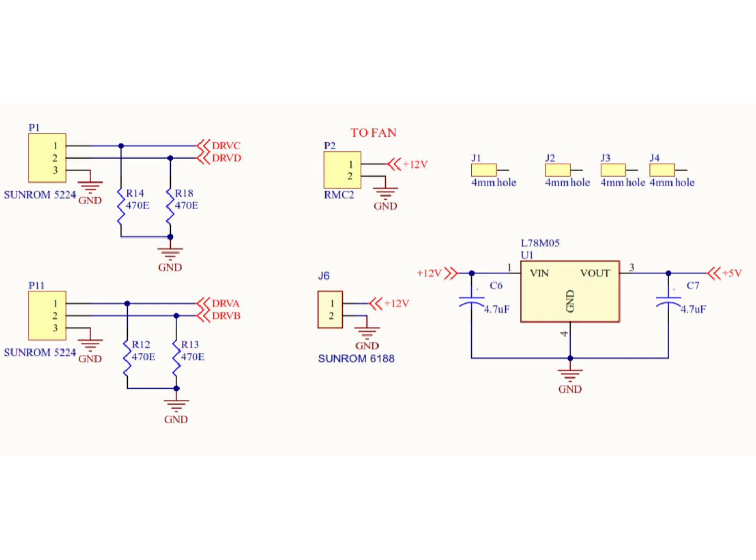By adding a low-value external pull-down resistor of 470 ohms, the input impedance is significantly reduced. This makes the control inputs much less susceptible to noise pickup, improves immunity against EMI, and ensures that the gate driver inputs remain in a well-defined logic state during resets, startup, normal operation, or cable disconnection.